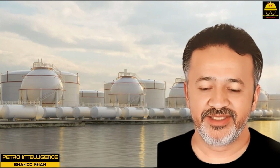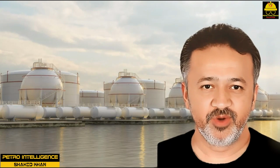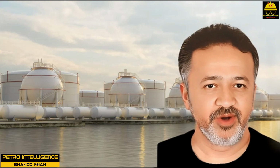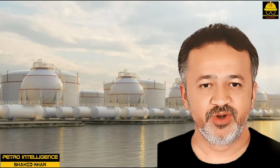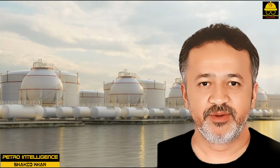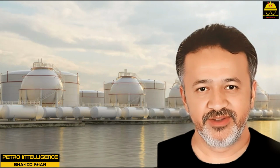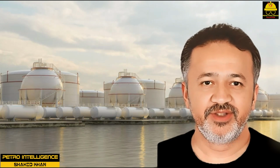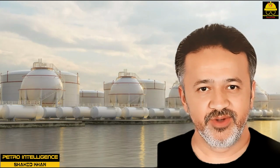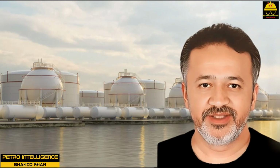The vapor space in tanks storing materials having a low vapor pressure at the storage temperature is usually too lean to explode. The vapor space in tanks storing very volatile materials is usually too rich to explode. In some tanks, however, the vapor space would be nearly always in the explosive range if air were allowed to enter. Gas-blanketed tanks are used to store these hazardous feedstocks. They are also used for other stocks when contact with air or moisture would be harmful to the product.